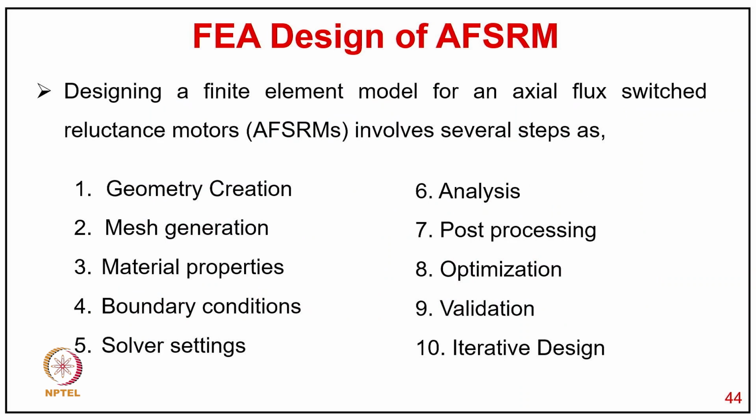So designing a finite element model of an axial flux reluctance machine involves several parts: first, geometric creation; second, mesh generation; third, the material property; fourth, the boundary condition; fifth, the solver setting; sixth, the analysis; seventh, post processing; eighth, optimization; ninth, validation; and tenth, the iterative design.